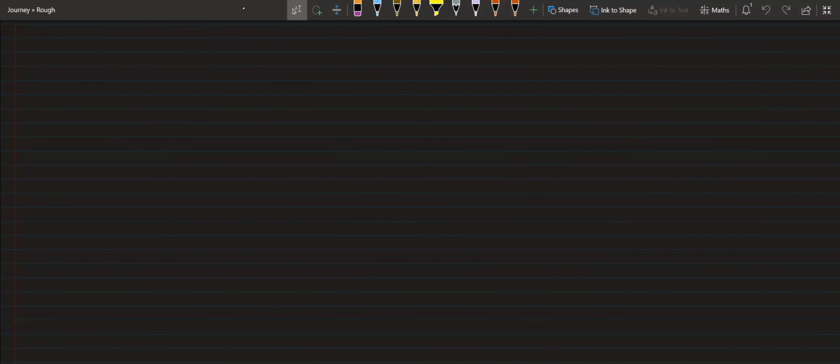So last class, we were discussing serial communication: what is the use of serial communication and how it is being used. So today, we will see how we can establish serial communication specifically in 8051. When I say serial communication, the first objective is to achieve the baud rate. That means how fast we can transmit the data.